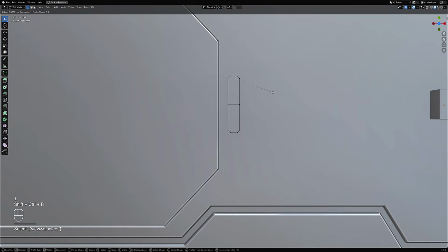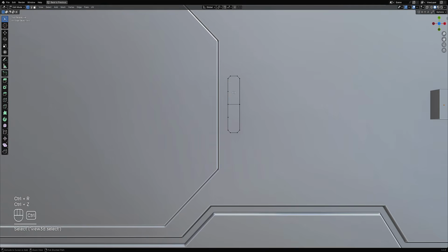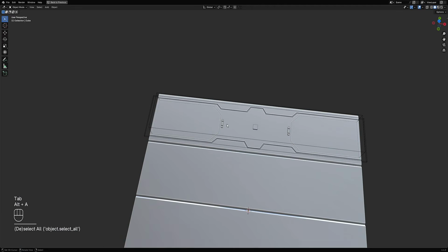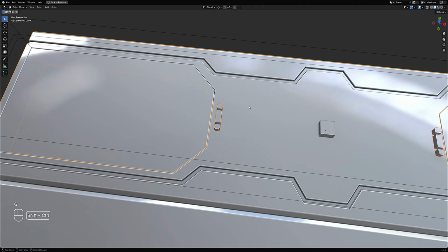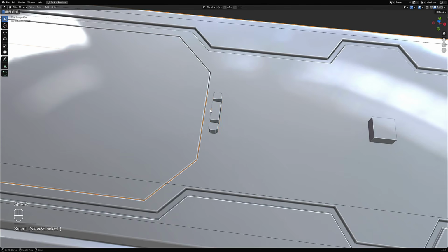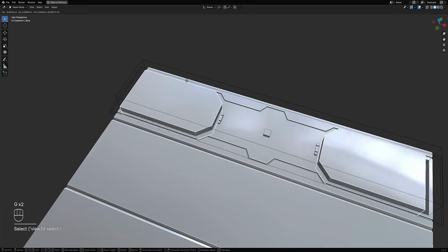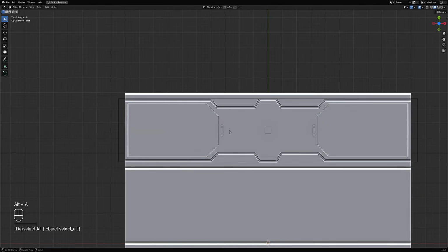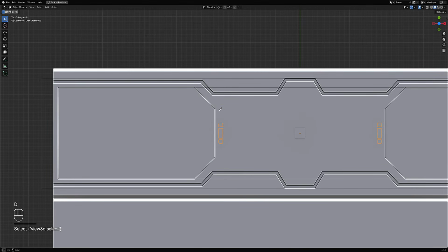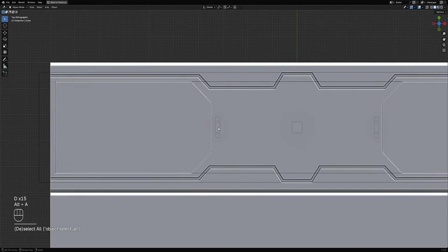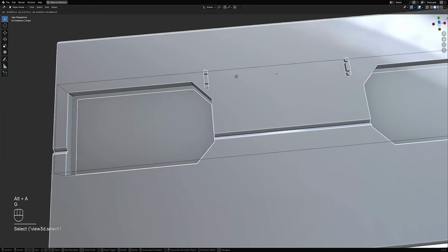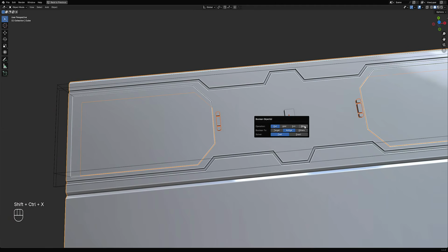It's probably bevel this like that, and there we go. And selecting our work mesh. If this detail is inside here, you need to pick this result of the slice operation. But in this case, since this is inside the source object, we're going to pick the source object. Click, click, and Boolean object, slice again.